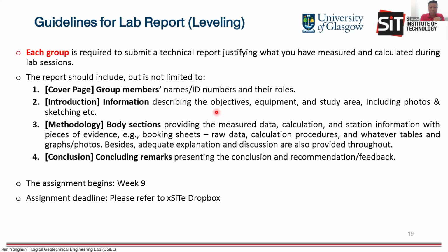You need to provide your measured data and your calculations, and the station information with the pieces of evidence, for example your booking sheet, your raw data, and your calculation procedures. And also how you check if there is any error during the calculation, and whether there is any misclosure. All this needs to be captured in the body section.